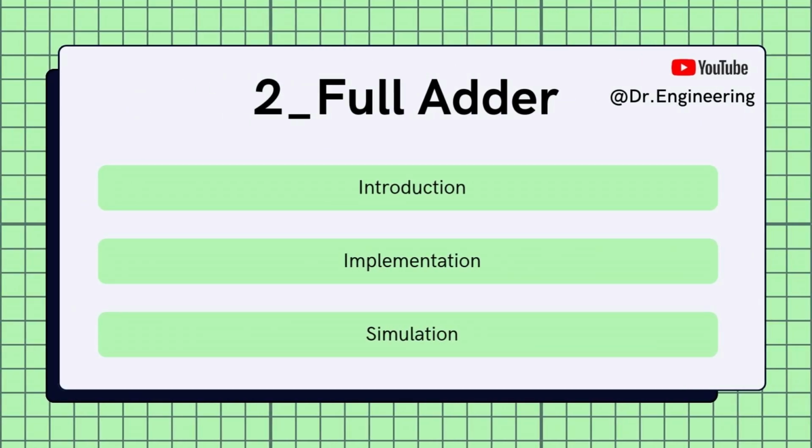That's it for today's lesson. We've introduced the full adder, implemented it in VHDL, and simulated it using a test bench in Vivado. The full adder is a key component in many digital systems, so mastering it is crucial if you're working with FPGAs.